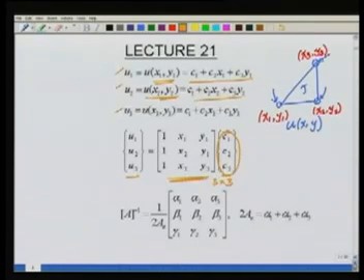So what we end up getting is, I call this matrix A. So A inverse will be 1 by twice the area of the triangle, we have called it tau, into some coefficients alpha 1, alpha 2, alpha 3, beta 1, beta 2, beta 3, gamma 1, gamma 2, gamma 3, and we can write the area of the triangle A tau in terms of these alpha 1, alpha 2, alpha 3. That's okay.